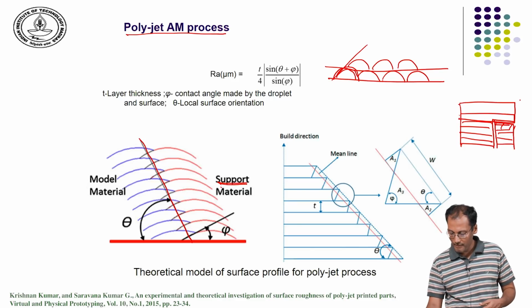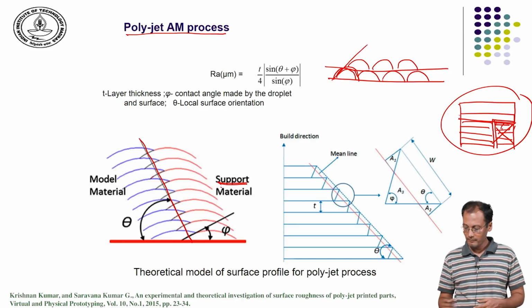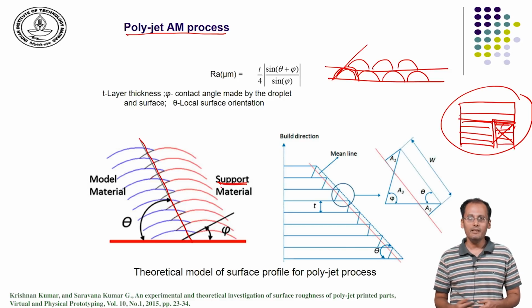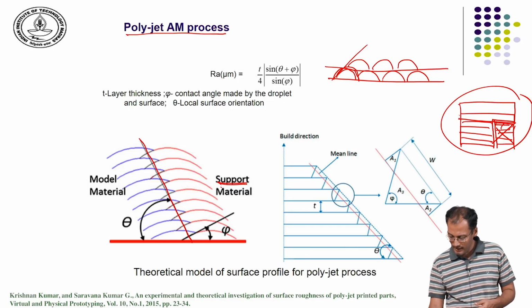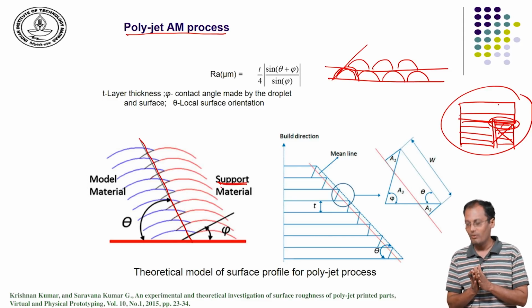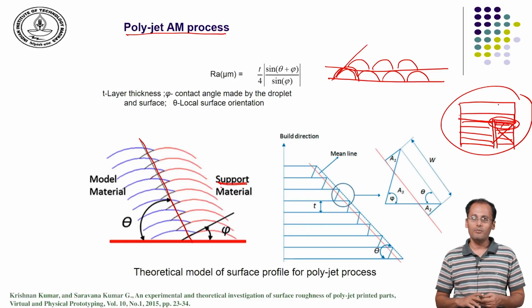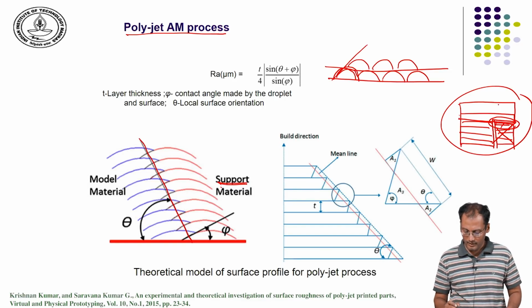Once the complete fabrication is done, this support structure is removed. The presence of the support structure increases the build time, and wherever the support structure is abutting the model, the surface irregularities are typically more, and one has to go for post process to remove such surface aberration.